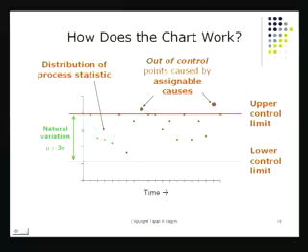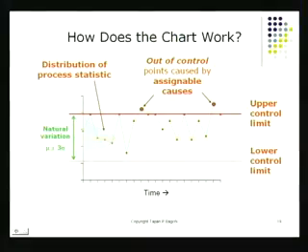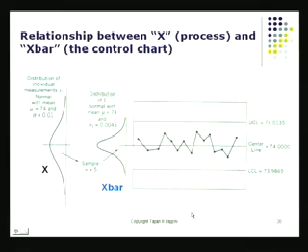When there's production going on to produce hundreds and thousands of these parts, you don't want these parts to be produced such that they violate the specification limits or are unfit for the user's use. These are not going to be good news for anyone. So you plot the chart and try to see, are there any points that have gone beyond the control limits? If they have, we have to stop the process and do some investigation.